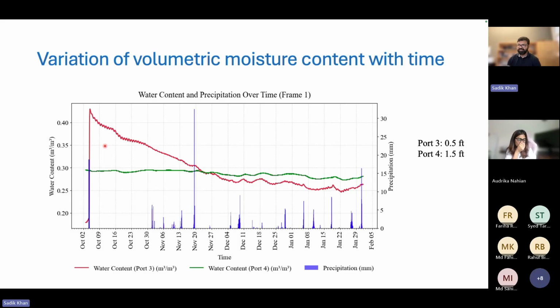But once we planted the vetiver grass, it is a game changer, because what it does is try to pull off the moisture from there. And when it pulls off the moisture, the moisture content keeps dropping. I personally feel this is extremely helpful for the slope, because when it reduces the moisture content, the overall dynamics has changed, and the dynamics really helped us to mitigate the slope failures.